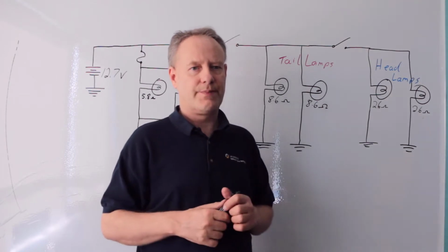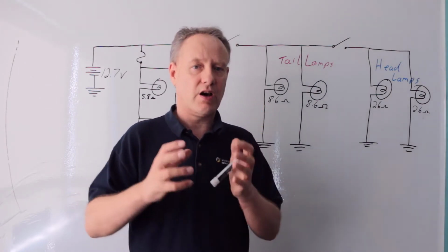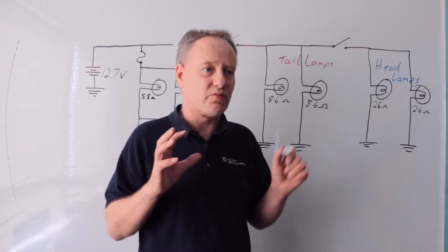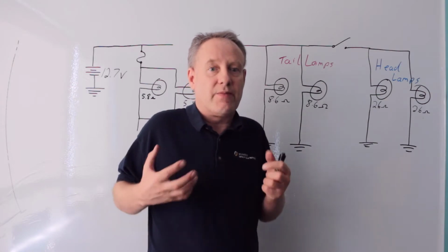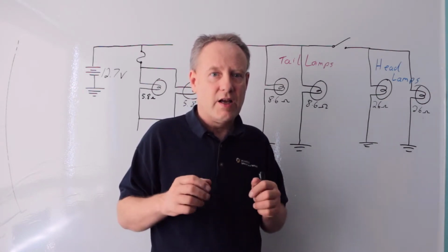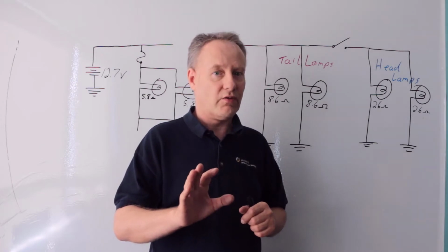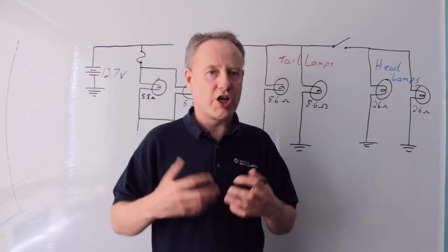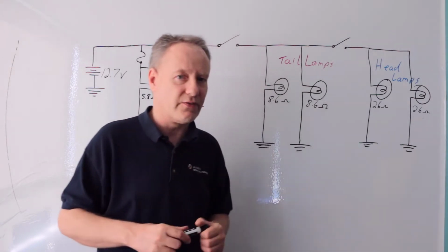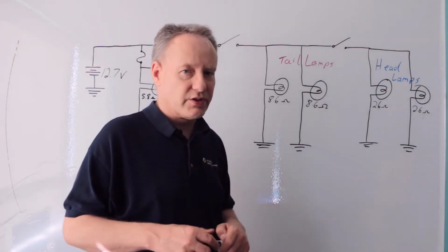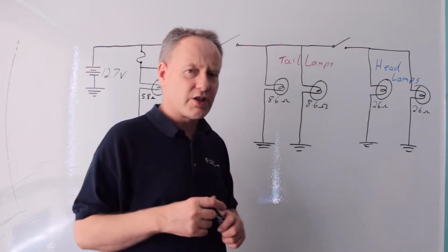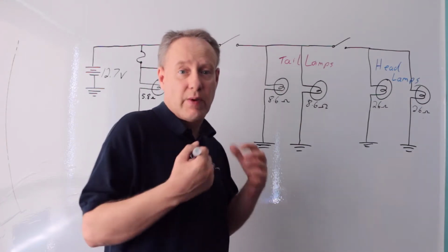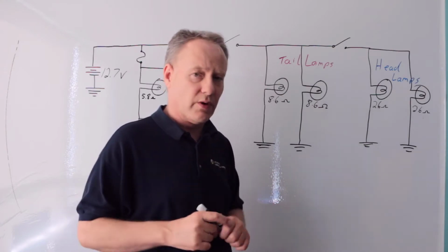When the charging system is happening and there's an alternator in the car, when that alternator comes on, it goes up to about 14 volts, maybe a little more. You may have regulators in your system, so if there are things sensitive to high voltage, a regulator says this thing gets 12 volts only. We're not talking about regulators right now. I just want to say that as the alternator charges, it kicks the voltage up, sometimes to 14 volts. Depending on the type of control system and the age of your car, that fluctuates a little more or less. So we're going to calculate all of our fuses on the rated voltage for the battery. So 12 volts, we're going to roll with that.